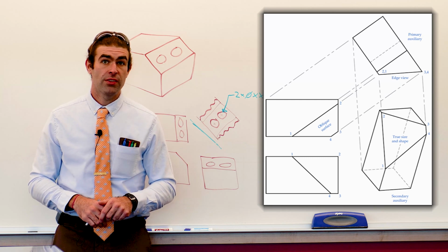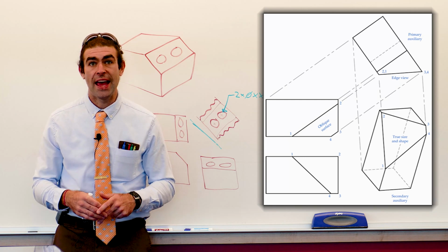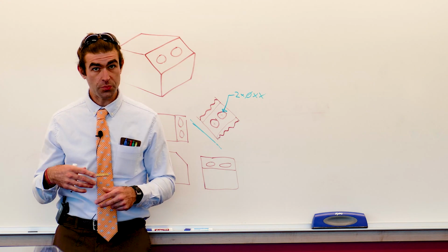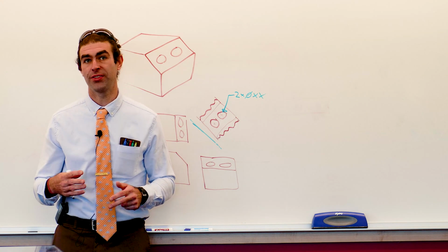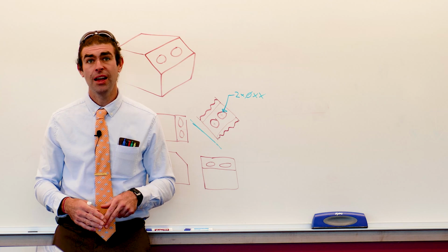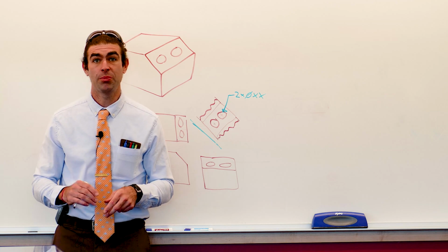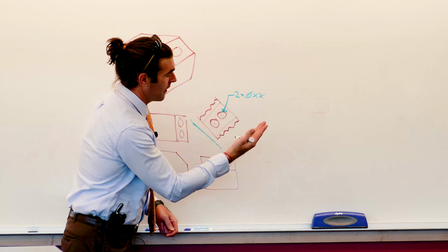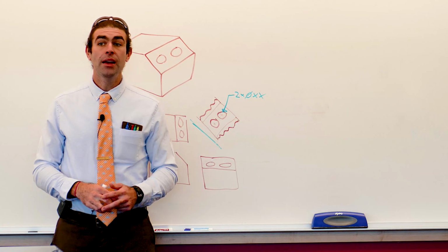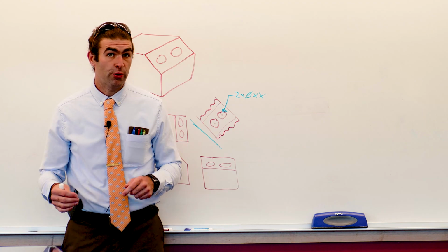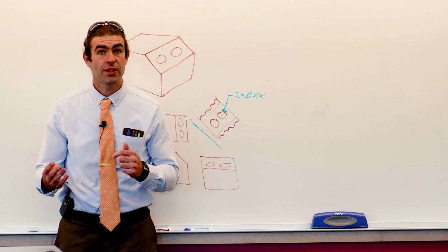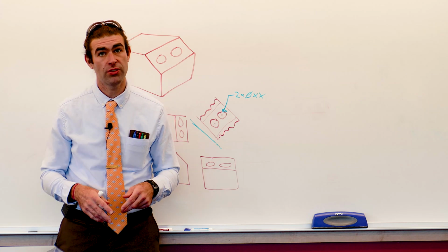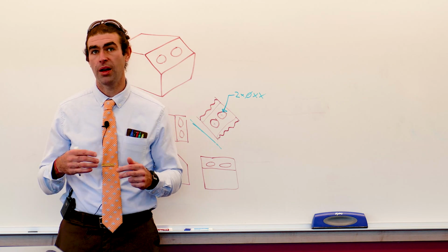In this situation, sometimes you might just want to dimension a CAD model and send that off, or you could consider just dimensioning it in a note if it's something like a 3D chamfer. Again, it doesn't come up too often, but that's what a secondary auxiliary view is. You're projecting once and then projecting again. So that's all I have for auxiliary views. Like I said, short video, pretty simple topic, used to show the true size and shape of features that don't appear in the principal